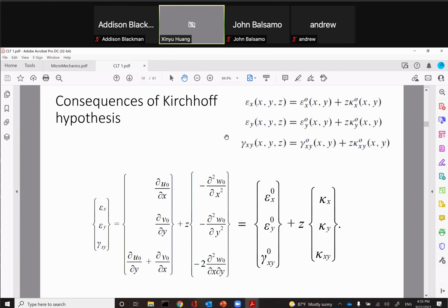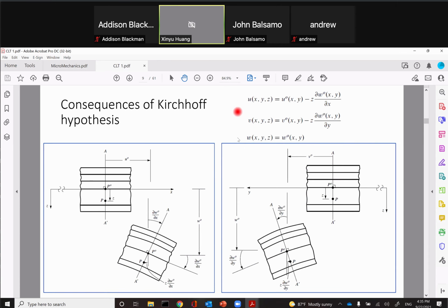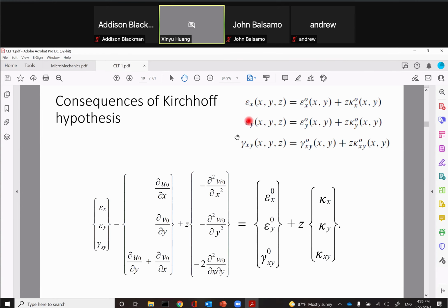So you can basically calculate this by doing the partial derivatives. If you use those equations we learned before, you calculate this strain. This is in-plane strain. Basically stretching x, stretching y, and a shear in plane. You plug these functions into the strain calculation function, you get this.